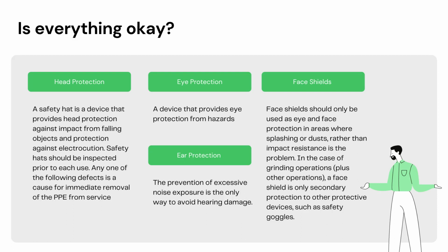Shells made of polymer plastics are susceptible to damage from ultraviolet light and gradual chemical degradation. The degradation first appears as a loss of surface gloss called chalking. With further deterioration, the surface will begin to flake away.